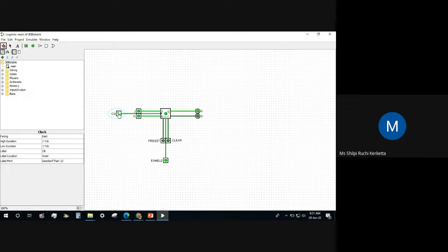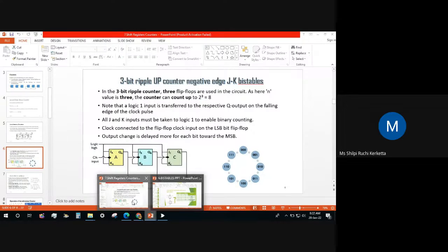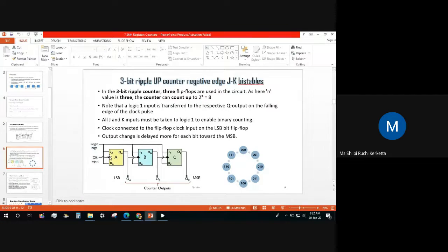Again it will give the opposite, so it is 1 0. If we give 0, then it is not working. Again it will give 1, and because this is positive edge triggering, we will get a 0. So it is reversing every time. Whenever we change the clock to positive edge, this Q is changing, it is just becoming the opposite. That's why we are using this JK flip flop for our circuit. Here we are using this JK flip flop for a counter.